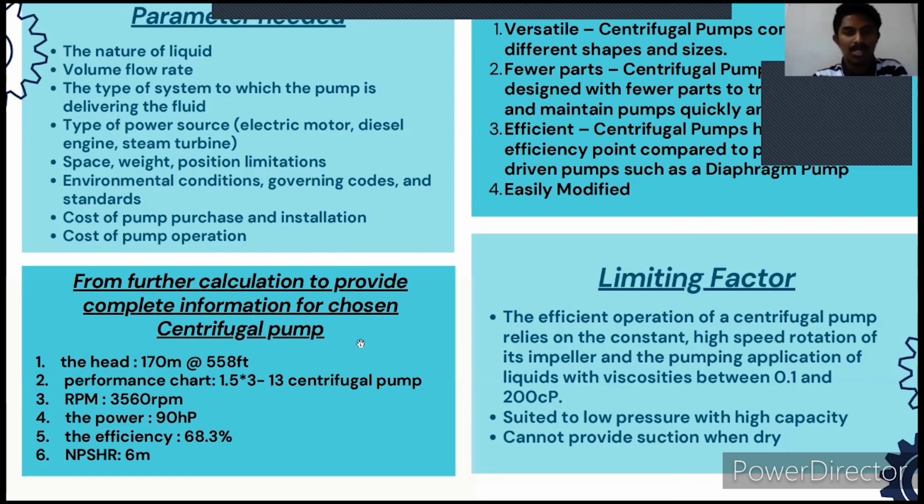The assumption was the size and the length of the suction and discharge lines. In this case, we decided to use DN80 Schedule 80 for the suction line pipe, while DN50 Schedule 80 for the discharge line pipe. Meanwhile, for both, the length assumed was 30 meter.